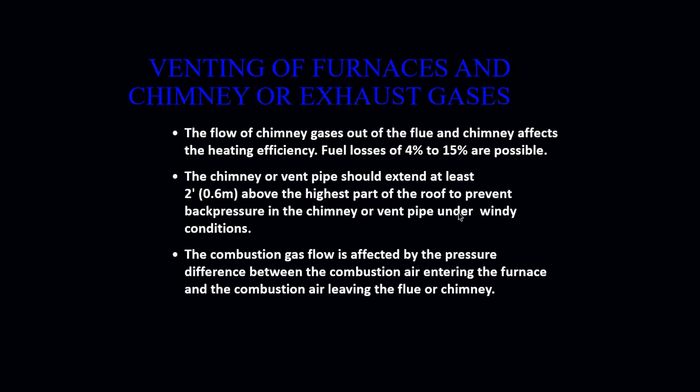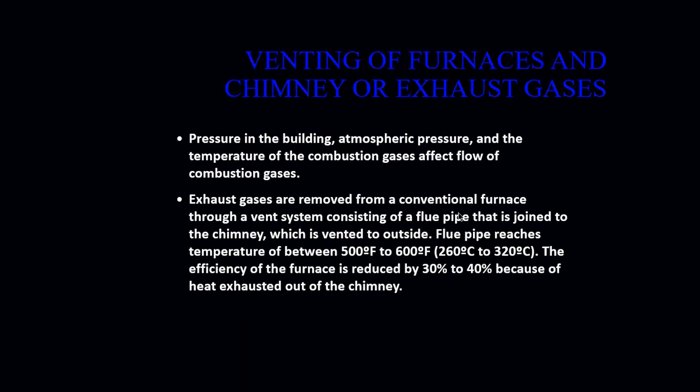The combustion gas flow is affected by the pressure difference between the combustion air entering the furnace and the combustion air leaving the flue or chimney. Pressure in the building or atmospheric pressure and the temperature of the combustion gases also affect the flow of your combustion gases. Okay, exhaust gases are removed from a conventional furnace through a vent system consisting of a flue pipe that is joined to the chimney, which is vented to the outside.